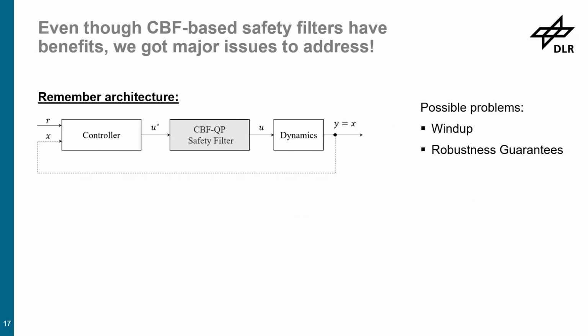When you put a safety filter just right behind it, your integrators will wind up, right? Because they will try to force the system to follow the reference because it has no idea that the safety filter is not allowing that, right? So in order to cope with that, you would need anti-wind-up schemes to ensure stability of the system, right? Otherwise, you will have issues.